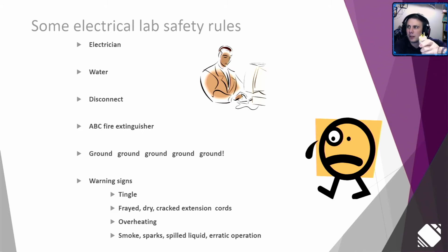So on your typical plug, you've got your line and neutral, your hot and neutral connections, and then you've got this longer stub, and that's your ground stub. If you have a GFCI, it's going to trip out if you've got a fault between line to ground, and that's the intent of it, is to protect your system.